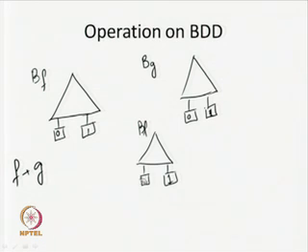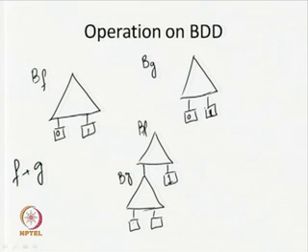So, in that particular case, we have seen that in this particular 0 node, we are going to put this particular BDD bg, and 0 and 1 are the terminal nodes. So, if f is 1, then the functional value is 1, and if f is 0, then we look at the valuation of g. Depending on that, I get the functional value for f plus g.